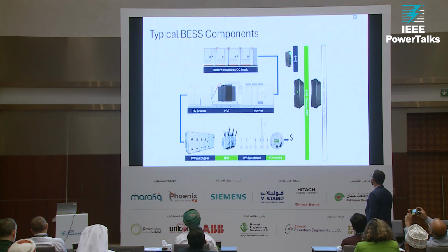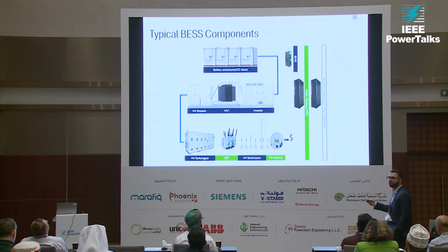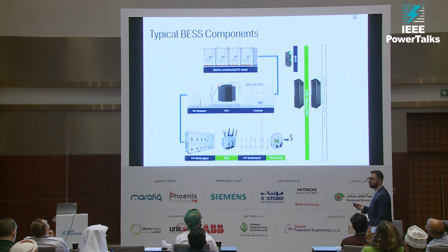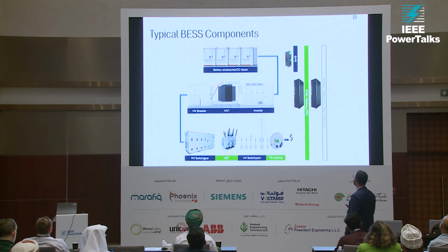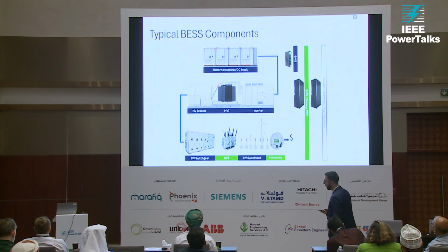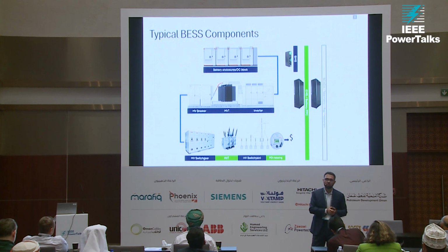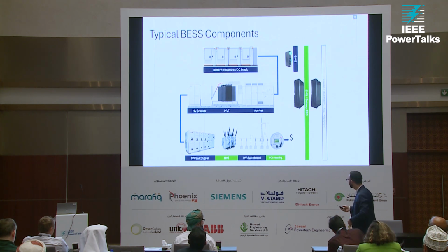substation type design. On the control level, there are two new components that are added to an energy storage system. In a traditional substation, you have your SCADA, your metering, your power plant controller, and all that. So that's easy. On a battery, you have 3 levels of BMS. BMS level 1 is on the module, BMS level 2 is on the rack, BMS level 3 is on the container. Then those BMSs talk to something called an energy management system. The energy management system takes the data from the BMSs, takes the data from your cooling systems, for example, takes the data from your fire alarm systems, takes the data from all the subsystems within the system, and does the intelligent processing of that.